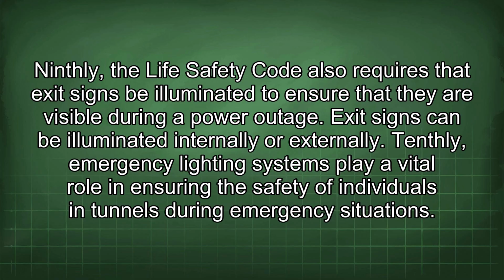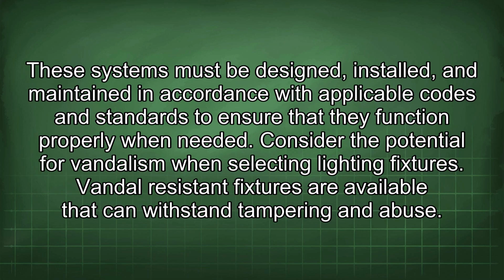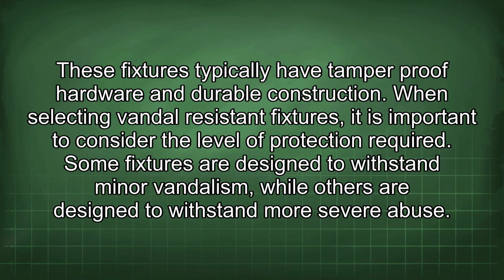Tenthly, emergency lighting systems play a vital role in ensuring the safety of individuals in tunnels during emergency situations. These systems must be designed, installed, and maintained in accordance with applicable codes and standards to ensure that they function properly when needed. Consider the potential for vandalism when selecting lighting fixtures. Vandal-resistant fixtures are available that can withstand tampering and abuse. These fixtures typically have tamper-proof hardware and durable construction.